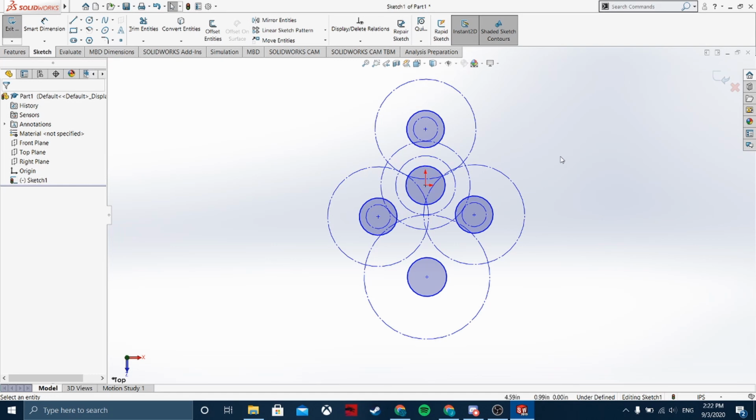The whole point of CADing is to eventually CNC this plate, and what the CNC does is it makes holes. So we only need solid circles for where it's going to make holes. Gears are not holes. They're just there. They're going to be attached to a bearing that goes inside those holes. So that's why I'm making all these construction.